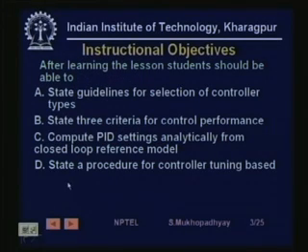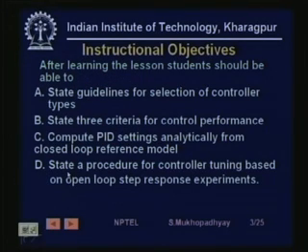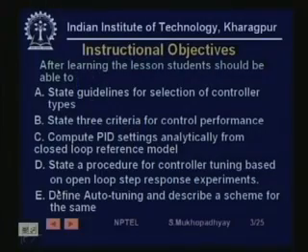and in some cases where an exact solution is not possible, because a reference model may not be available, we sometimes set controller parameter settings based on experimental data, and there are two basic approaches. One is an open loop approach, which is based on step response. So, you should be able to state a procedure for doing that, and the other one is for closed loop. So, that one also, you should be able to do.